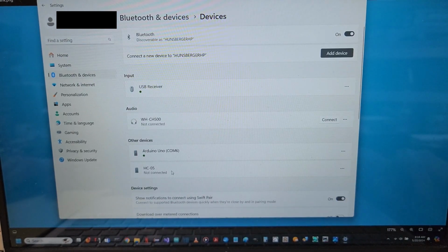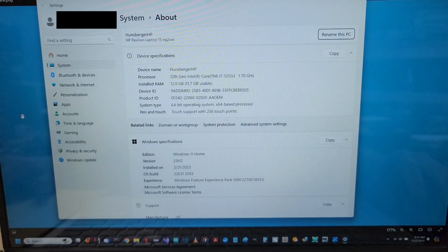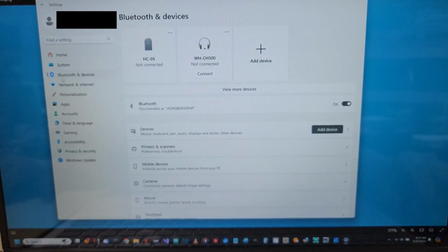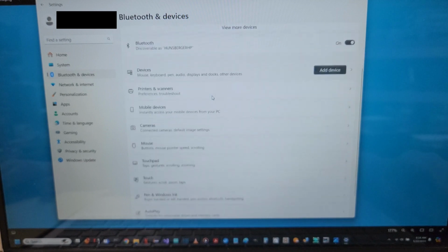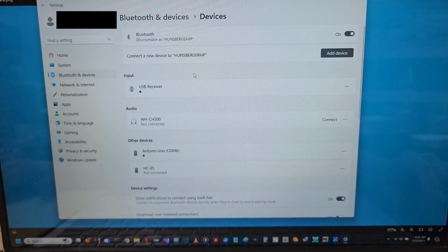Next, in the dialog displayed, the HC05 device will be listed provided it's powered up. You have to have it powered up before it can be seen, of course. But if it's already listed, then that device entry in the list has to be removed and then added again. Now, ask me why, I don't know.